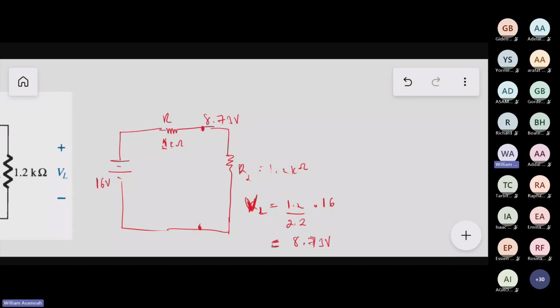Yes, sir. Now, we've connected a Zener diode that only conducts when the voltage is 10. So will the Zener diode conduct? No, sir. So this Zener diode will never conduct. For it to conduct, how do we properly bias this? We increase the load resistance. Great, excellent. So either we choose a higher resistance for RL or we reduce the resistance for R, so that this is properly biased.